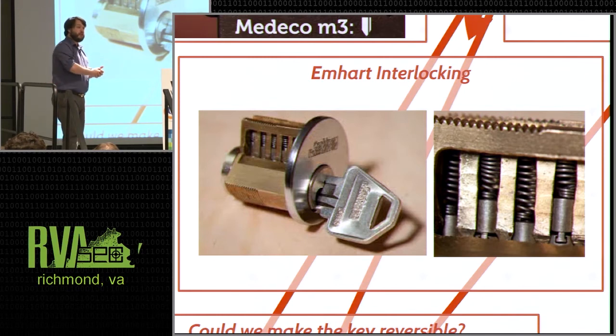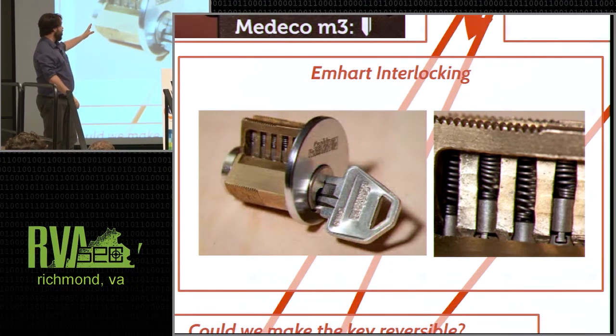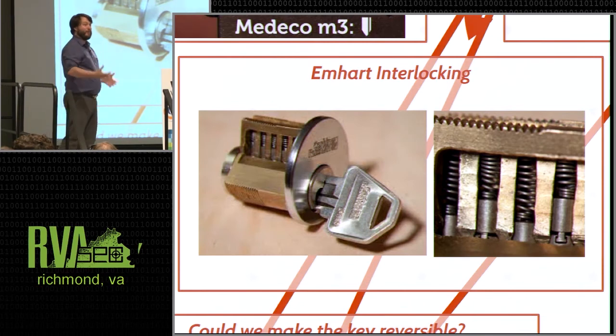When the key is fully inserted into the lock, the pins can rotate far enough that all of the joints are facing outward, and they'll all be sitting at the shear line. The plug has channels cut into it that the bottom of the driver pins can rest in, so they stay in alignment, so they can be recoupled when you turn it back around to the locked position, and they can separate from one another.